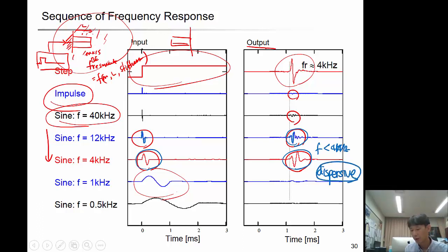So then it's difficult to get the phase velocity. Instead, we have to look at the group velocity. When we determine the group velocity, it's better and easier to pick the arrival time when the rising is very steep. Steep rising helps arrival time picking.